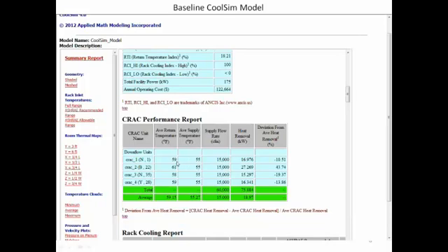But look at some of these return temperatures, Liz. I mean, in one case, I've got a delta of 3 degrees. 3 degrees on crack number 3. Because it's blowing 15,000, it's too high. So you have a situation here that we've got way too much airflow, not enough delta T, and this crack number 3 is running way off its design center. These are designed to run at 20 degrees delta T, and I've got 3.